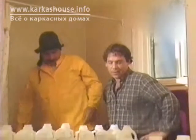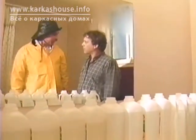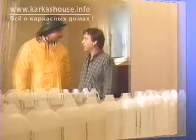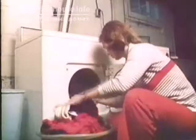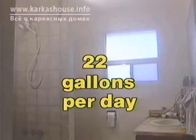See those bottles there? Those bottles contain the amount of humidity generated by a family of 4 in a 24-hour period. Wow, it's a lot of water. Just from showers? There are lots of other sources as well, David. Washing dishes, laundry, cooking, and also from the house itself, from wet basements or new framing, concrete that's curing. Between the family and the house, you can actually generate as much as 22 gallons a day. And all of that is generated in the form of water vapor.